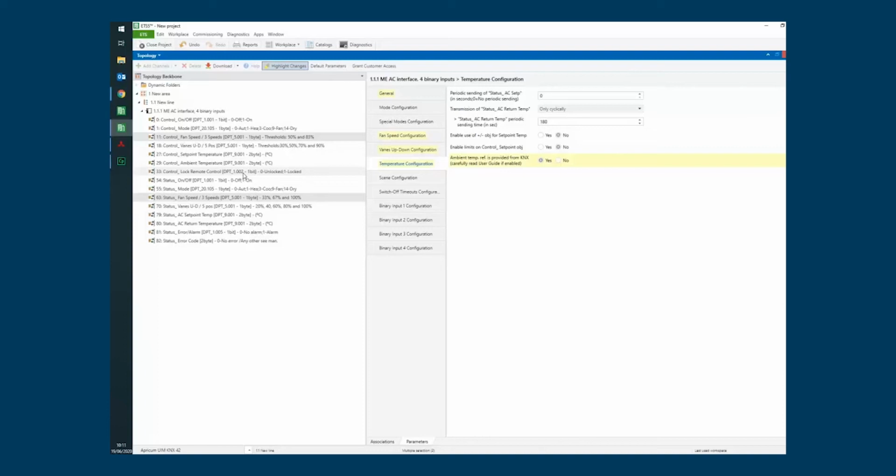So, basically, knowing these 3 values, the user set point on the KNX side, the ambient temperature on the KNX system, and the reference temperature of the AC unit, the interface will recalculate the real set point for the air conditioning unit to adapt to the real situation. The only reason that the Intesis gateway behaves this way is that the AC unit doesn't allow overriding the reference temperature.